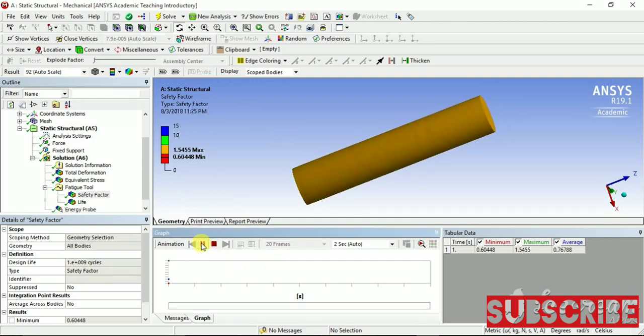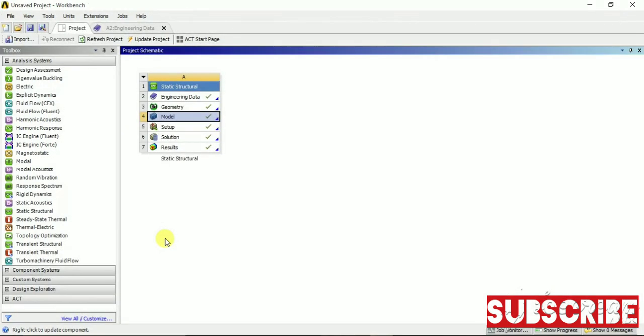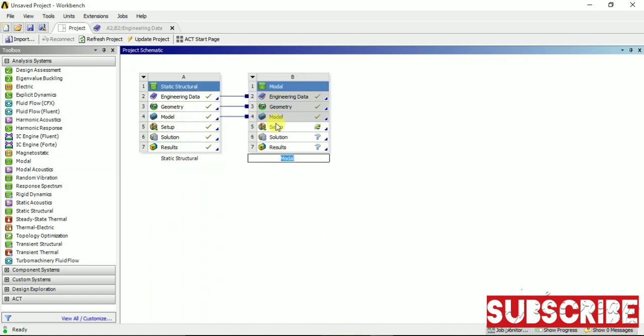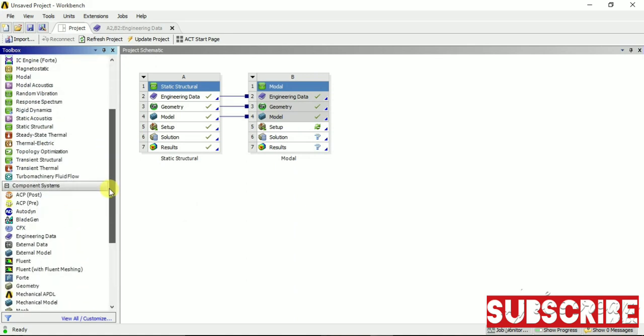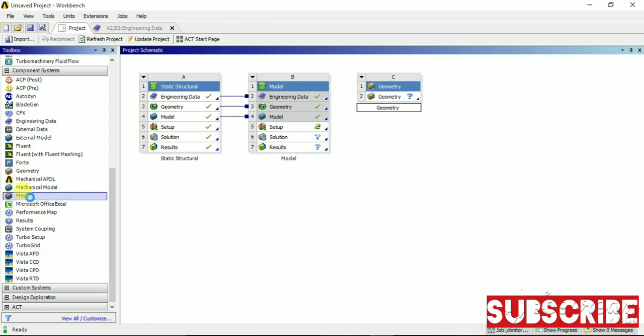These are different options to view the results. Okay, now we will close that. Now one more thing I want to say, that if you want to add some more modules or connect this static structural to another, for example the model, just click on it and drag it and share it to the model. Now the data from this static structural will be shared with the model module, and you can do the analysis likewise here. And if you want to use a component of the module separately, you can use the modules from here. For example, geometry can be used separately and then linked to other modules. Mesh is different, you can do it likewise.